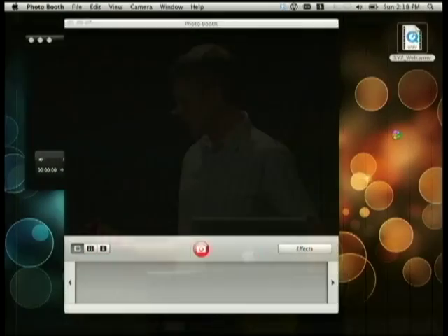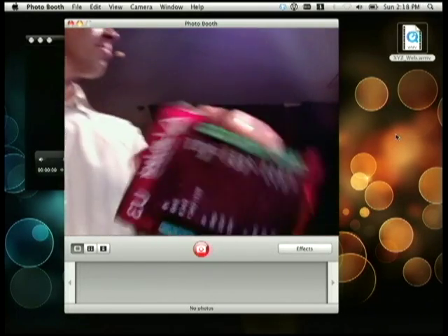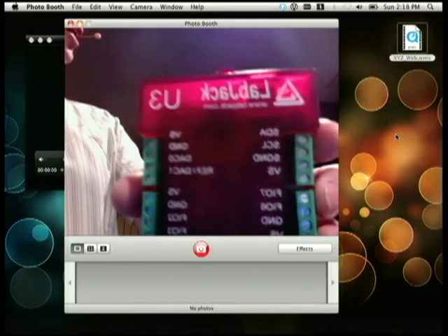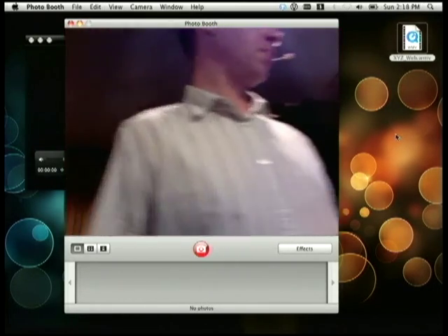So first off, this is a LabJack. It's a block of plastic with screw terminals, and hopefully you get a feel for the sort of size and that. You can see, oh, that's reversed. You get the idea. These are sensational for just hooking up real-world electronics where you just want a simple, robust interface. There are Python libraries for it, there are libraries for a range of other languages, and the thing just works. I've used this for a car engine management system where it was out in the filth, the dirt, the rain, everything, and the thing just works.